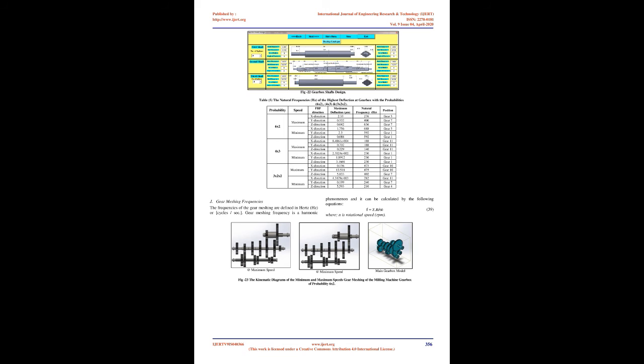The solution of the gearbox consists of 3 steps. In the first step, choosing the number of speeds and motor speed, maximum and minimum speed, motor power, and progression ratio. In the second step, entering the minimum number of teeth, pressure angle, efficiency, width factor, and strength of gears, and shaft strength. The third step is set to enter width and efficiency of bearing, inclined angles, and reduction ratio of the belt, pulley diameter and width and distance between pulleys' axis.